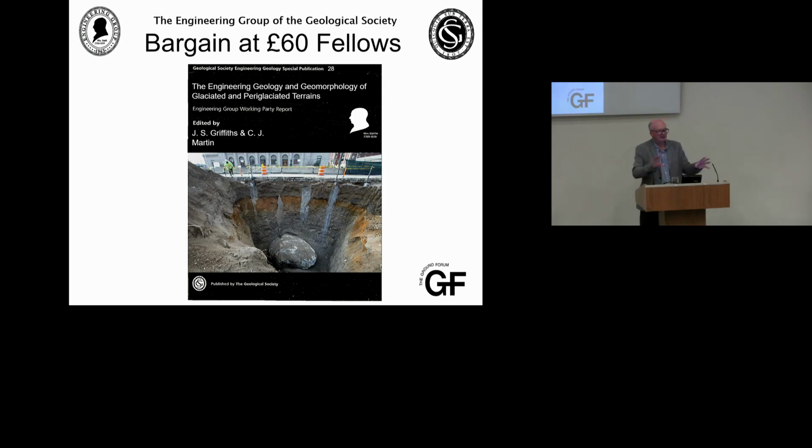Yet, as we're starting to see from some of the site work, it is not like that in these terrains. And there's a lovely example across the road here. One of the talks that's been here previously: there's a basement development across in St James's where they did 6 boreholes, 5 of them were in London clay, and then suddenly one of them was in the Lambeth group. And then they started to dig some trenches, and they had some Thames gravels with a reverse fault going through the Thames gravels. Because it wasn't benign, it was that level of variability.